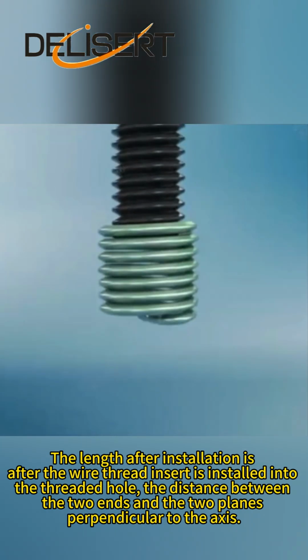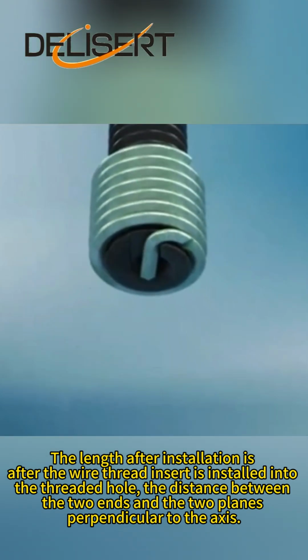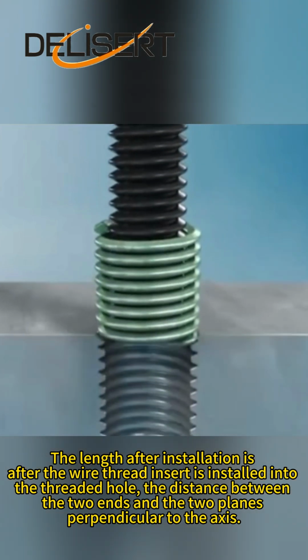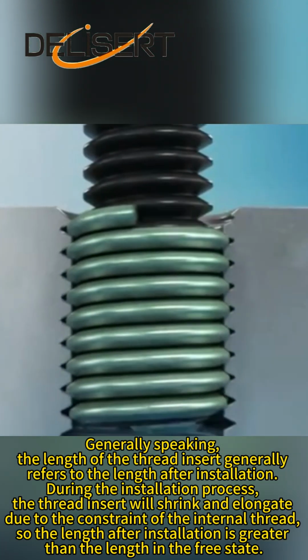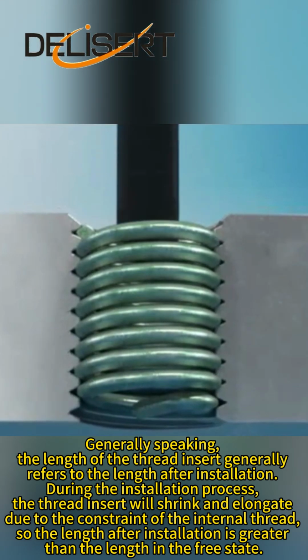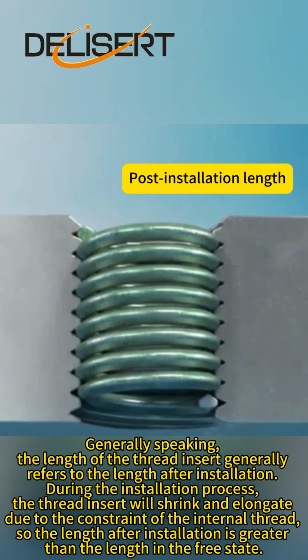The length after installation is the distance between the two ends and the two planes perpendicular to the axis, after the wire thread insert is installed into the threaded hole. Generally speaking, the length of the thread insert refers to the length after installation. During the installation process, the thread insert will shrink and elongate due to the constraint of the internal thread, so the length after installation is greater than the length in the free state.